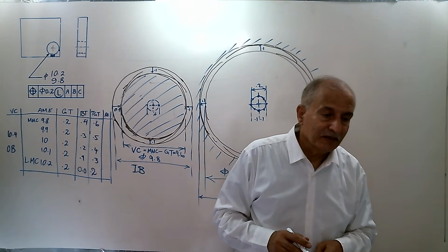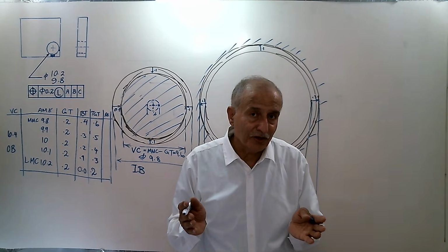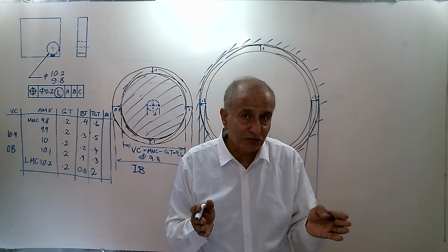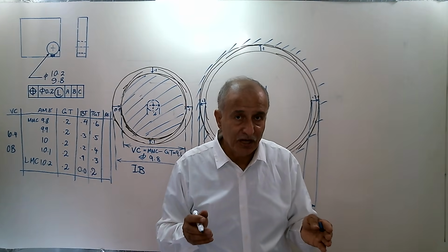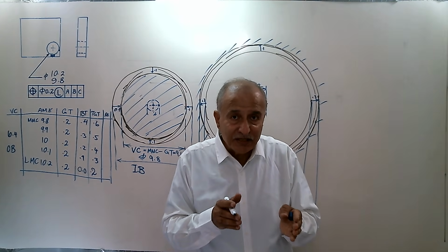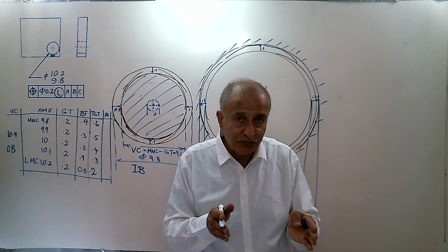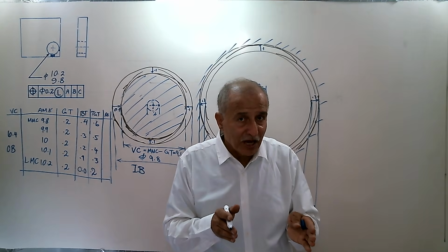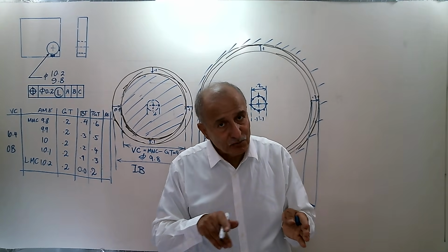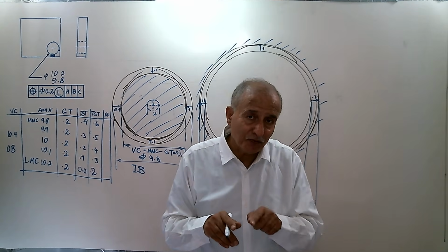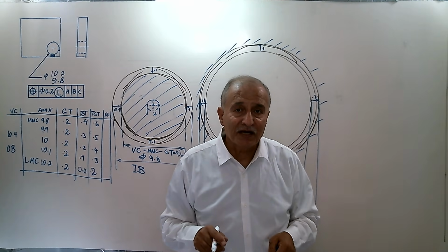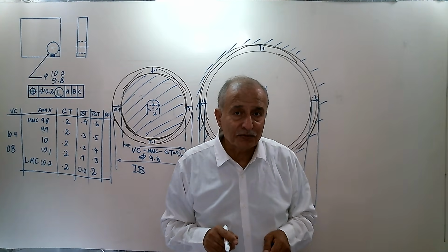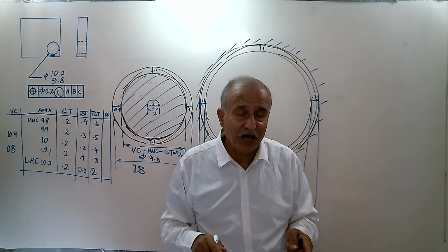It means that the manufacturer, if you make the hole at its maximum size, largest diameter, which is 10.2, the axis of this 10.2 can be 0.1 displaced to the right, can be 0.1 displaced to the left, and then you draw a circle with 10.2 plus 0.1 here, 0.1 other side.